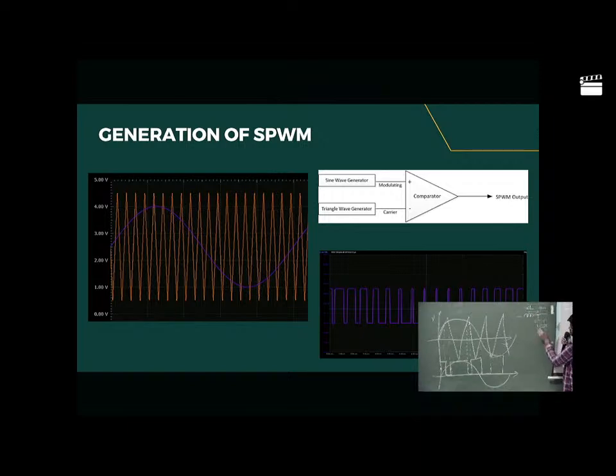Now this capacitor here is grounded. For high frequency signals, the capacitor offers low impedance, so it will divert them to the ground, and for low frequency signals the impedance is high, so it will block them and they just travel away. So this is effectively producing a low pass signal. Whatever these fluctuating components are, if you pass them through this filter, it will give out your continuous component, which will be a sine wave, right? Okay, is that part clear? Right, okay, awesome.